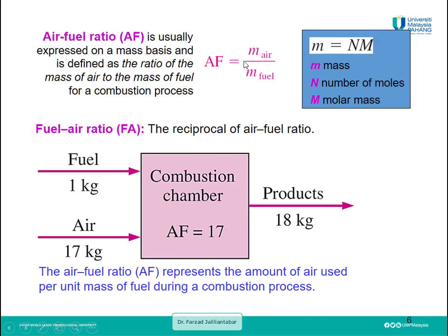To get the mass of air and mass of fuel from their molar masses, we can use this equation. The mass of air or fuel or any other substance is equal to the number of moles of that substance times the molar mass of that substance. And the reciprocal of the air-fuel ratio is called the fuel-air ratio. It can also be used to define this ratio between the fuel and air.